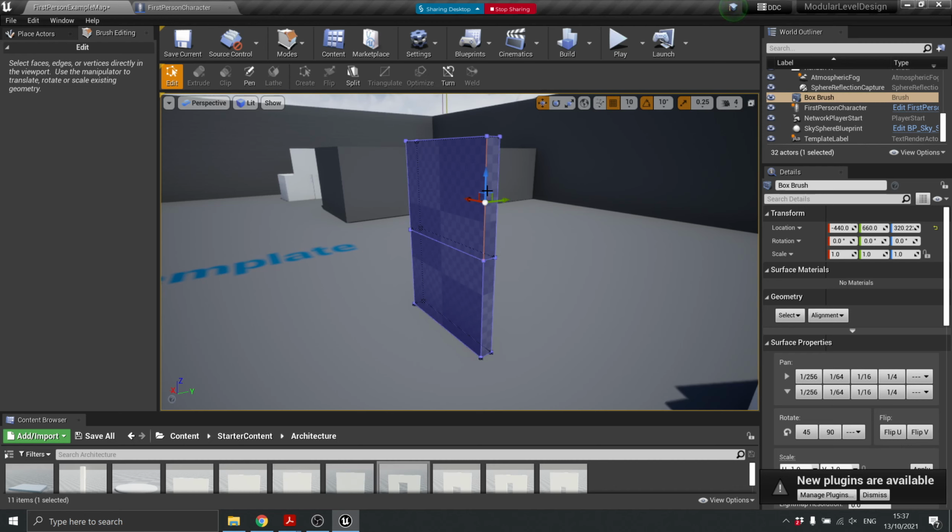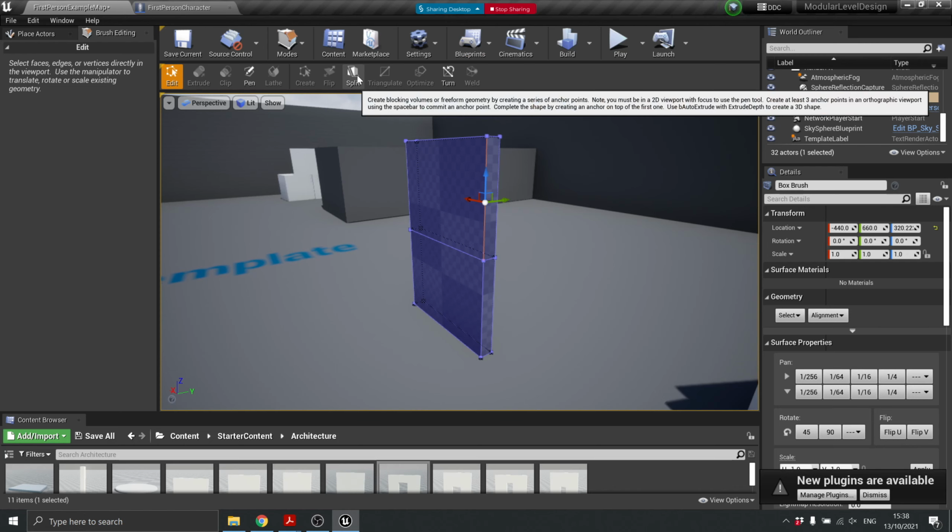it can be real tricky to get the edges. Sometimes it'll keep selecting surfaces. You just have to get the mouse right over the edge. Yeah. So it could be just one of them. Just one edge and hit split, and it should draw the line on it. No, it will always split along the line. Because we're only selecting a line, the only way to split a line is to put it in the middle. Right? I think it will always, let's see what it says when we select. So, we can hover over this and see what it says. I think it will always be halfway.